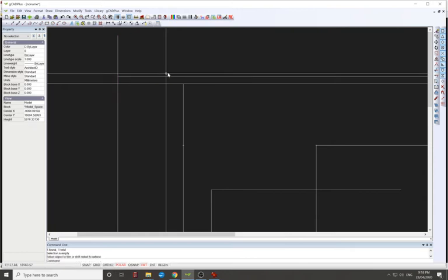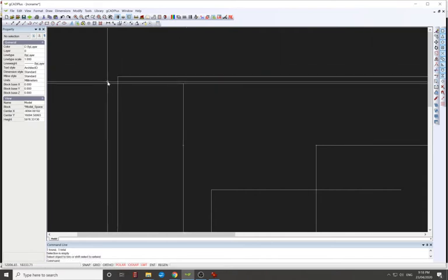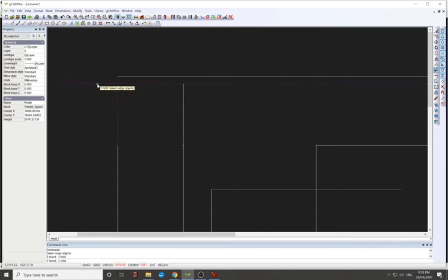Oh, okay. So trim. You select that, and then you select that. So if you want to cut this line off here, you've got to show the program where you want it cut to, not what you want to cut first. If that makes sense, because computers don't work that way. They're deductive, so it's like, that's where it's got to go to, and then no, actually I've done that wrong. So trim, that's where you cut to, right click, not left click, and then that's it.